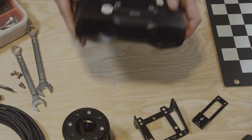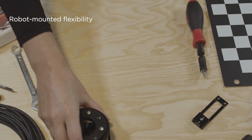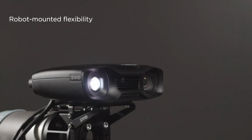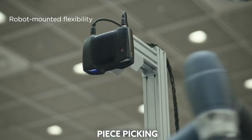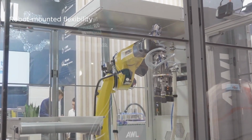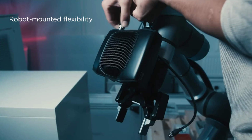I would also like to talk about the importance of robot mounting flexibility. Our cameras are designed to perform either in a static mounted configuration or directly mounted onto the robotic arm. When our cameras are mounted stationary, it doesn't present much of a challenge. It requires being mounted on the stand correctly, out of the clearance of the robot and at the right distance to be able to perform good data quality. However, when we mount the camera on the robot, it's another story.